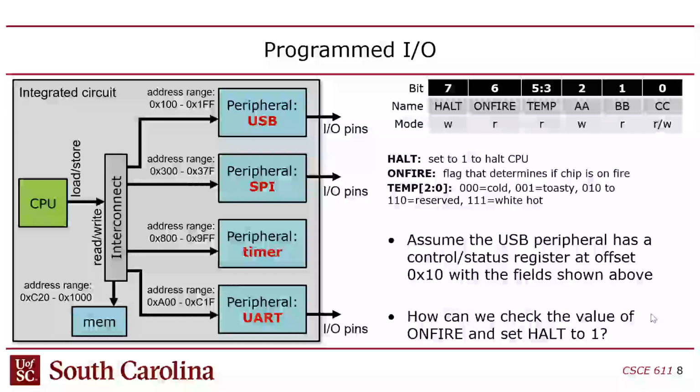I can't leave those bits in the middle because they'll be multiplied by 8, right? So if the temperature in there is, say, 4, it's not going to read as 4. It's going to read as 4 times 8 because they will have been shifted effectively to the middle of the register. So I'd want to shift those back to the right so I could right justify them. You guys with me?